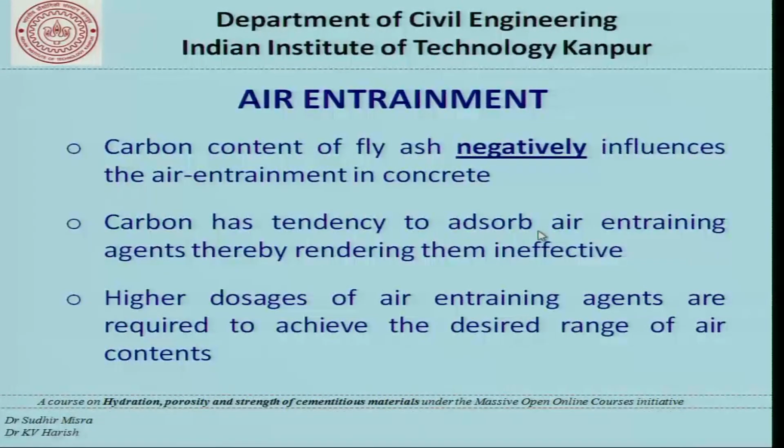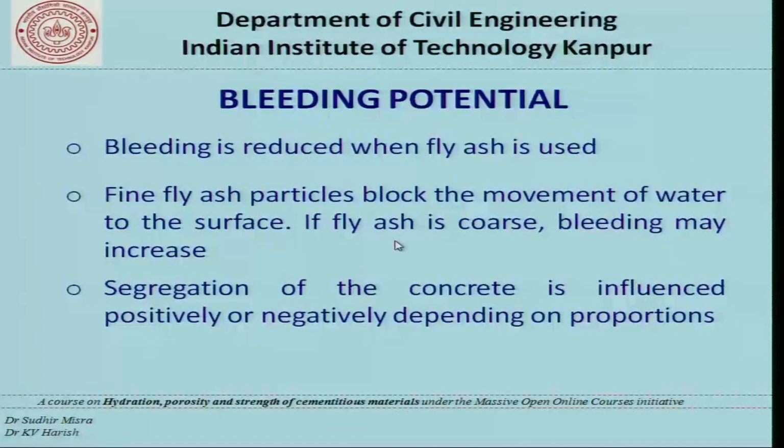Carbon has a tendency to absorb air entraining agents, thereby rendering them ineffective. Higher dosages of air entraining agents are required to achieve the desired range of air contents. Now coming on to the next property, which is bleeding potential. Bleeding potential is reduced when fly ash is used.